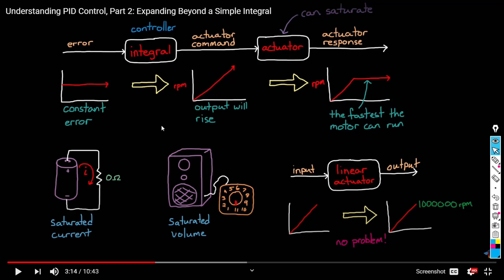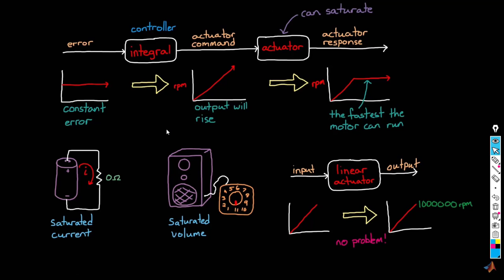So now we understand what saturation is. In real practice, your actuator will get saturated. So assume you send a control signal in which your actuator is saturated. You are in a scenario where your actuator is saturated. How will your PID behave, in particular, how will the integral term behave? We can figure out why by asking the question, how does our PID integral handle an actuator that saturates?